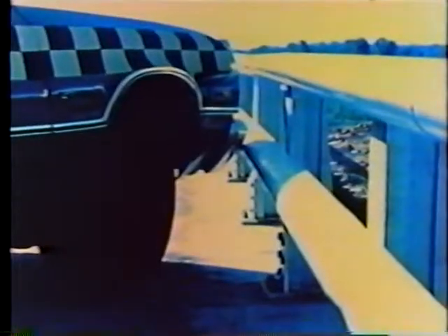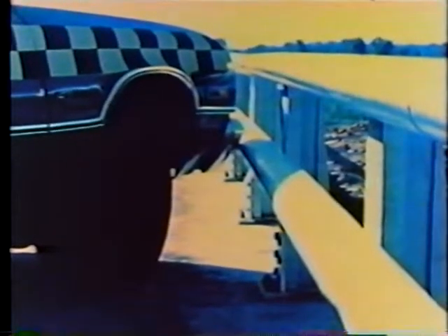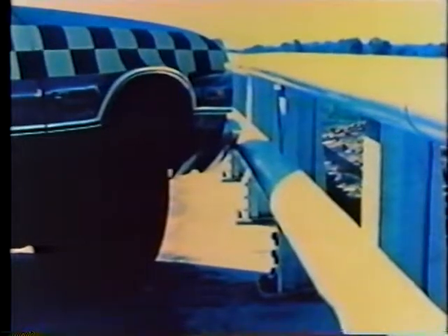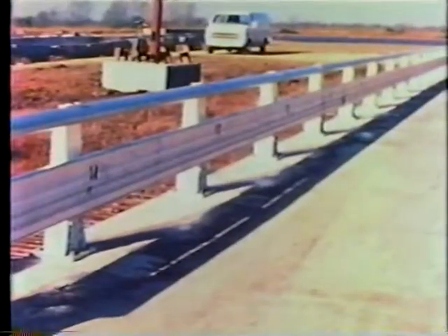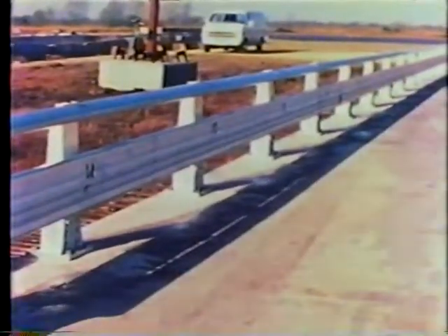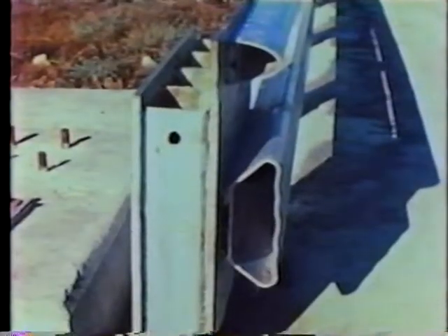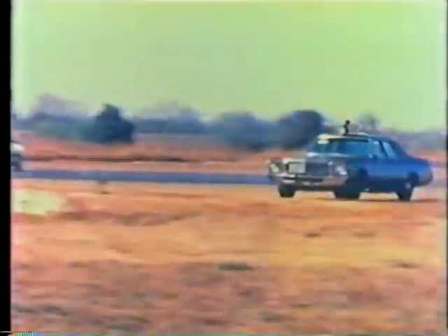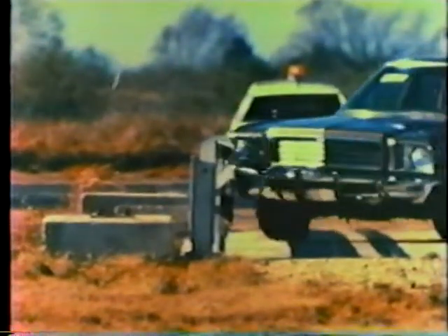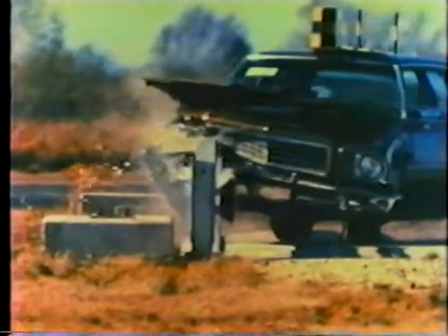There are problems with the arch in the post's base plate and the riveted post-to-base plate connection. This is a retrofit of the previous railing. The base plate has been flattened. The test car is successfully redirected. However, this railing is still below specification strength requirements.